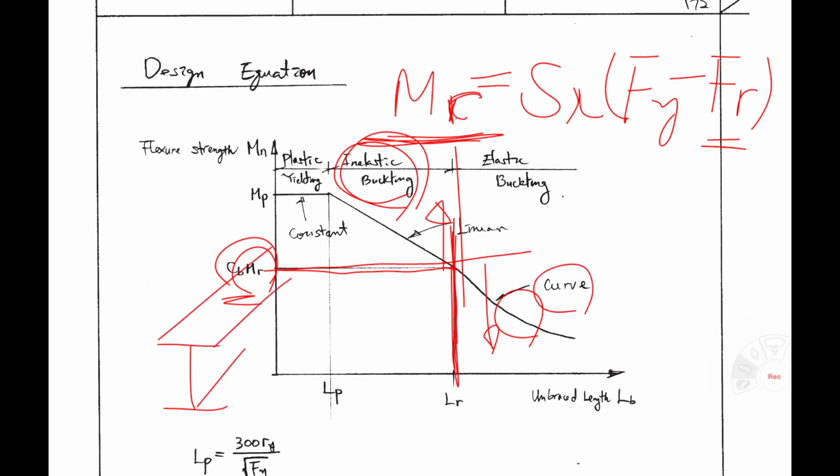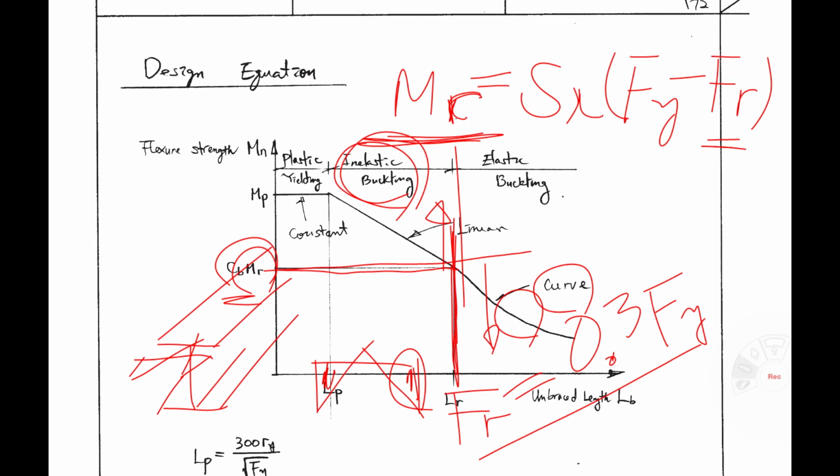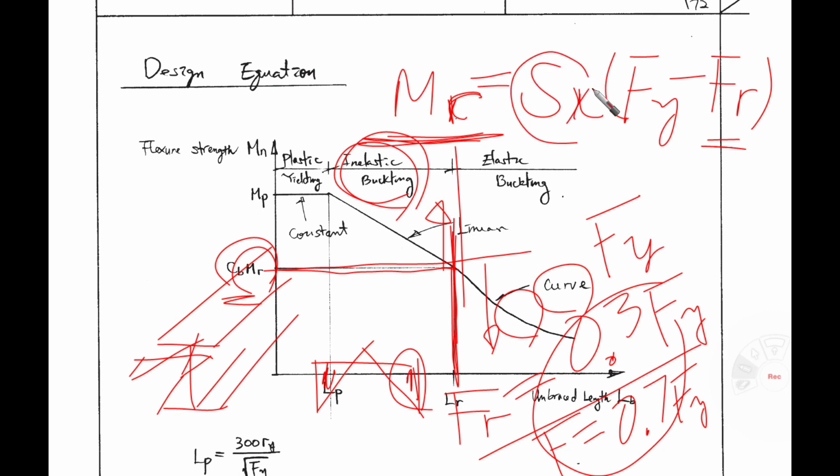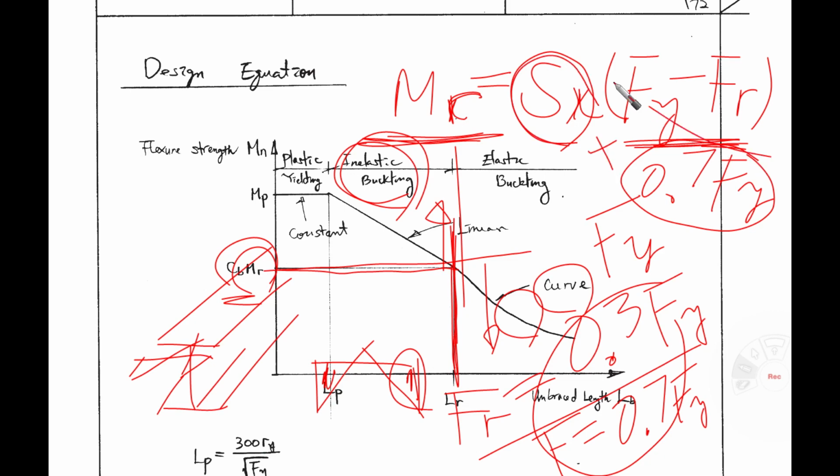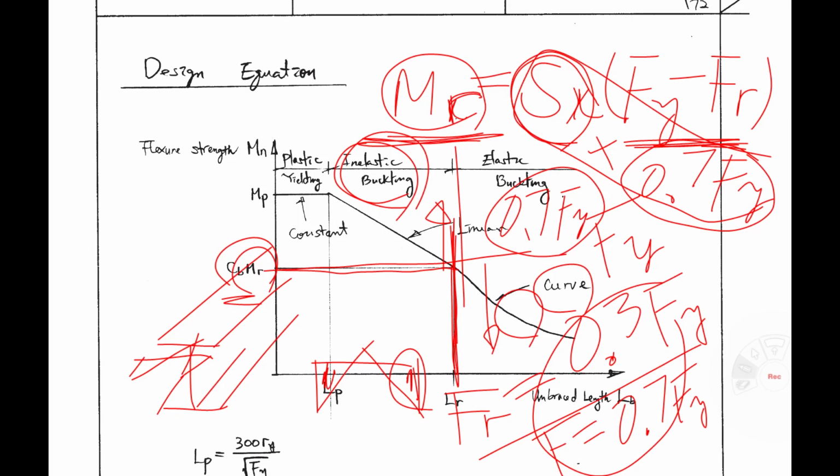This I-section has residual stresses. If I draw here like that, the tip part has compressive residual stress. Let's say this is 0.3 Fy. In that case, the stress due to the moment is, let's say, 0.7 Fy. If you add them together, that is Fy. Here, this one is the section modulus Sx. If your moment is this value, then the developed stress due to the moment equals 0.7 Fy, and your existing residual stress is already 0.3 Fy. We add them together, then it yields, right? Fy. So it yields from this tip part, at that point. So that is Mr.